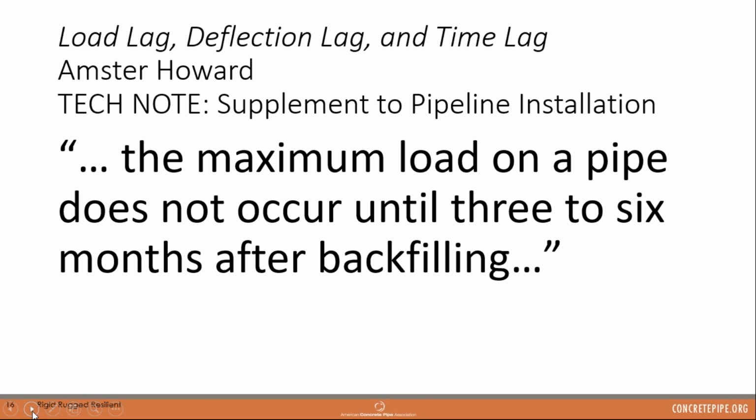This is reiterating my point that it's important to understand the timing of when that test occurs, because plastic pipe is going to continue to deflect to some degree over its lifespan. So you want to hit it at a critical point in the lifespan of that pipe. Some people say 30 days, but here we see that the maximum load might not hit the pipe until 3 to 6 months. So that might be one reason to wait until the warranty period runs up before you pull the mandrel through the lines, instead of just once at the 30-day mark.